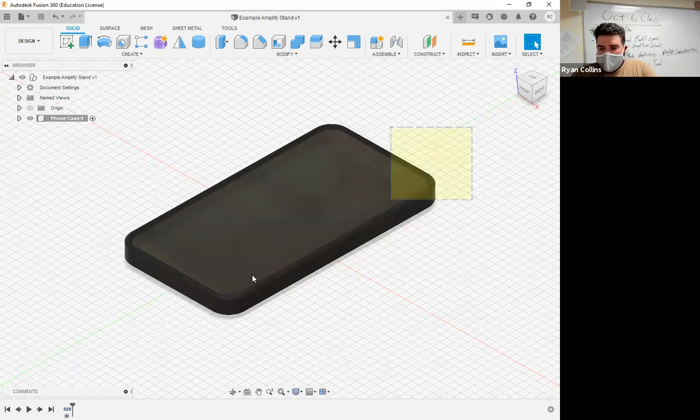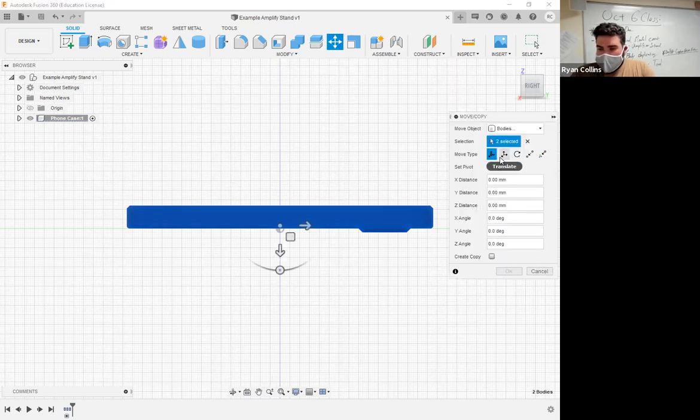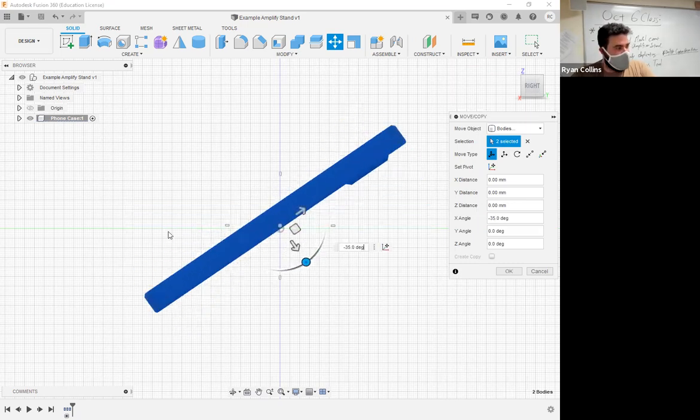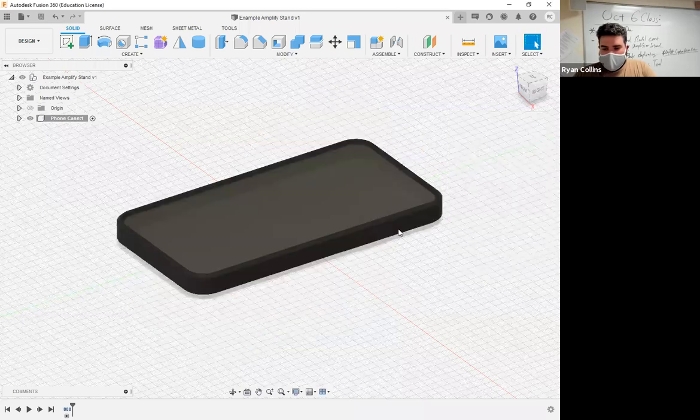Okay. Select all the things, go to the right side, and I'm going to move this, press M or use the move control thing. I want to set pivot, because if I just rotate from here, it's going to rotate the whole thing, but I like working on the axis plane, meaning that my current work plane is the origin XY plane. I would prefer to work from there. So let me cancel that, goes back.